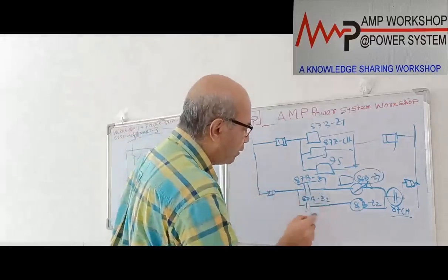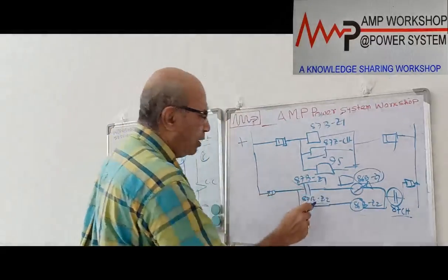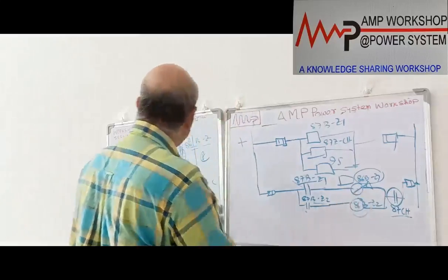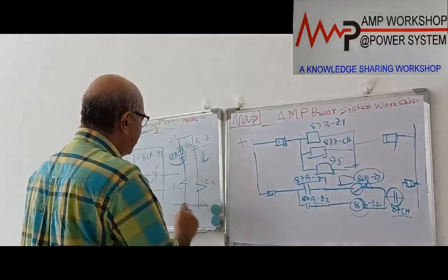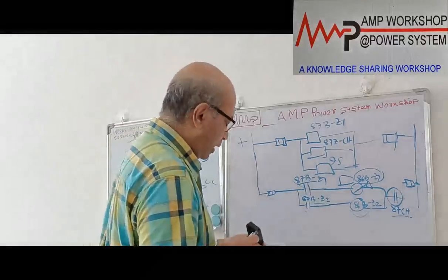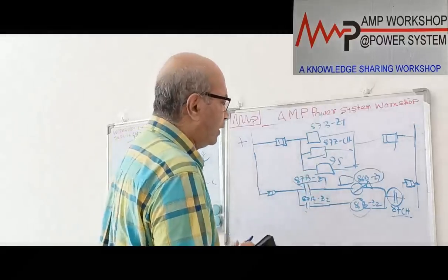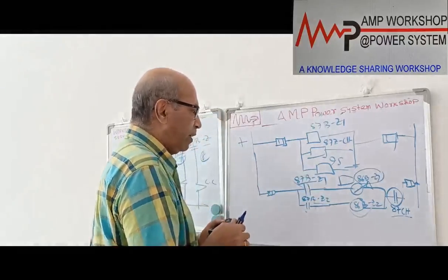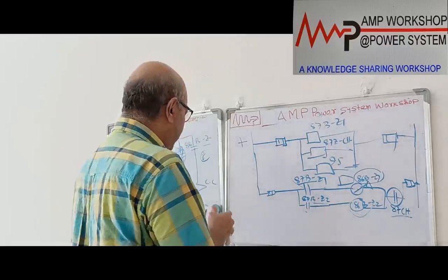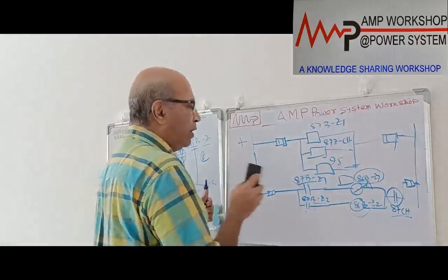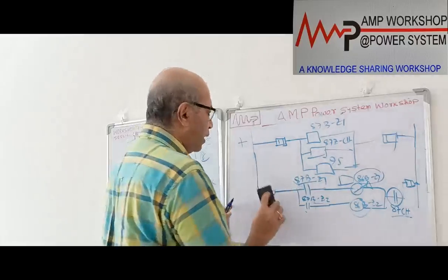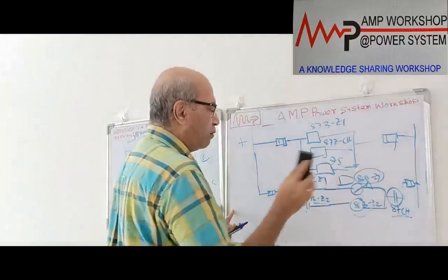Similarly, 86BZ2 for Zone 2 works the same way. When this relay operates, the breakers of the corresponding section will be tripped and closing blocked. Then similarly, for the 95 relay, the CT secondary wiring relay, when it operates we need an indication also for that. So now this is your tripping and closing part.